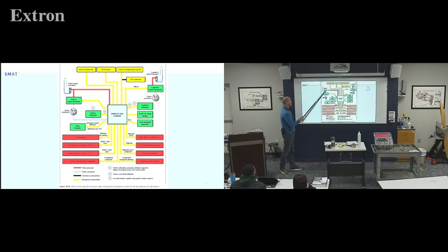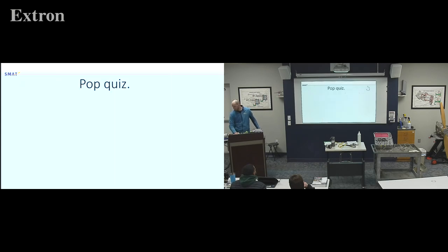But I only have two little pitot tube lines, one on this side. Static, there are more going to stuff, but where does my air data computer get static from? Right here. Basically one static line coming in, instead of running the static to the transponder and running it to my flight management computer and running it to flight blah, blah, blah. So the air data computer, or the digital air data computer, is going to take care of eliminating a ton of our lines for us so we don't have as many leaks. It's okay, it's not that bad.